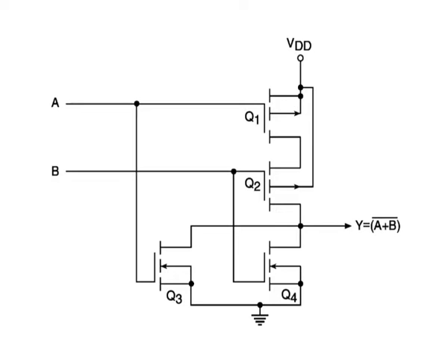This is possible only when both the inputs are in logic 0 state. This verifies one of the entries of the NOR gate truth table. When both the inputs are in logic 1 state, both the N-channel devices are conducting and both the P-channel devices are non-conducting, which produces logic 0 at the output. This verifies another entry of the NOR truth table.